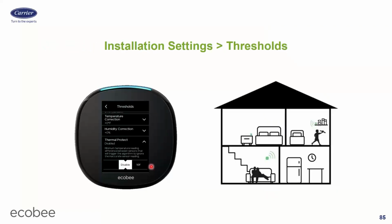Then the last thing on there is the thermal protect. This comes disabled. I turn this on, and I usually set it for either 10 or 15 degrees. What that does is, in this case, I have 3 thermostats: the stat, this remote sensor, and that remote sensor. If any one of them drifts, let's say I set it for 15 degrees, more than 15 degrees away from the other ones, I'm going to assume it's bad. I can't imagine a scenario in which the upstairs is 15 degrees hotter than the downstairs.